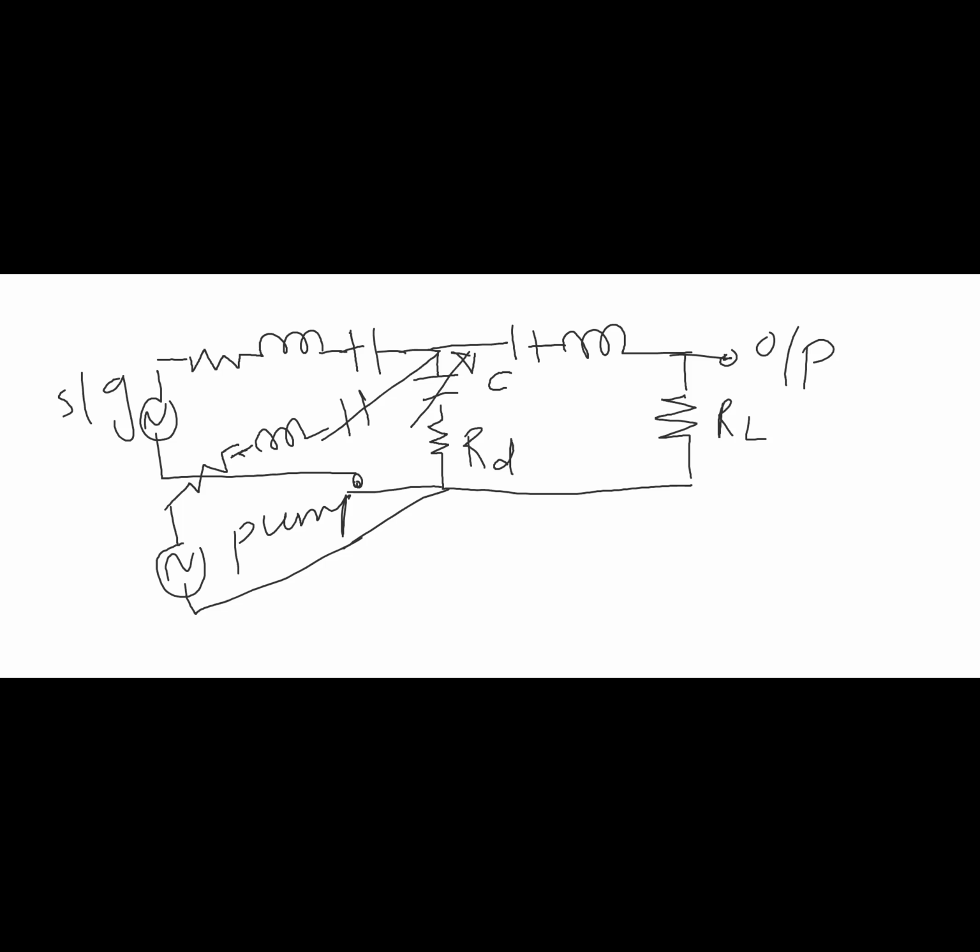Now what is the role of LC? So see, you are using what? Biasing potential to vary the capacitance of the diode. So that potential is what? DC in nature. Okay, square pulse is there, right? So that should not interfere with what? The other signal. So L and C play important role in that, right?